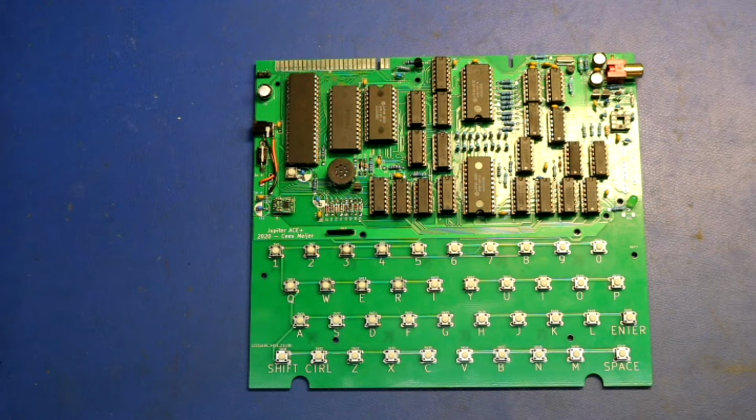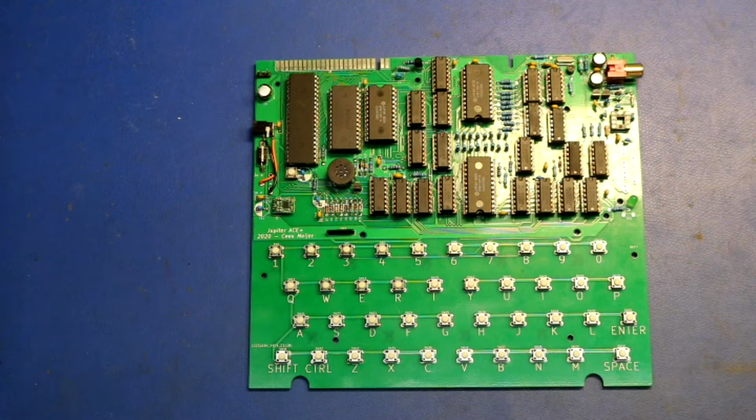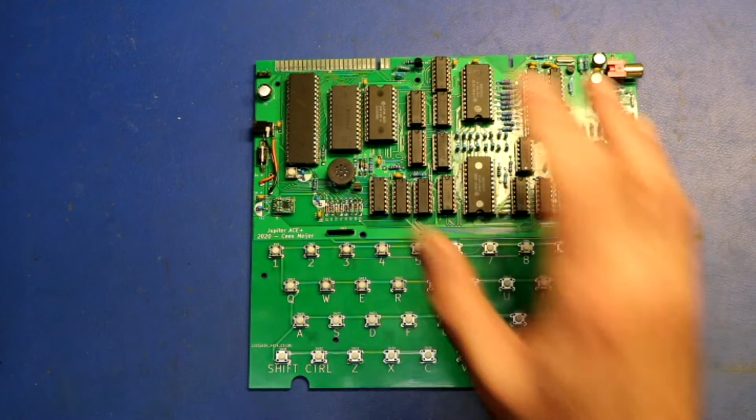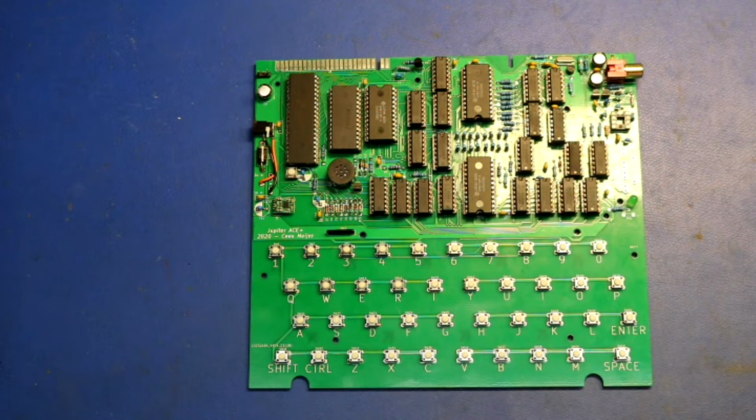Then I replaced any HCT chips with LS chips like were in the schematic. My thought there was that we've got these resistors where we're sharing the data bus, or sharing the address bus between data and address, based on whether you're reading and writing the video RAM or accessing the character RAM. There's all this weird bus sharing going on. I thought maybe the logic family was the issue there, with the HCT levels being a little different from the LS levels, and drive capability and such. But that didn't make any difference.